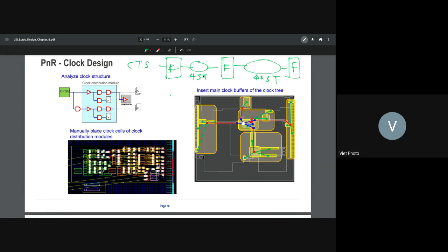So the thing is, because of 4 stage, I don't need this one to be fast. So that means even though the period from here to here is 1 nanosecond, now I will make the clock come in here, and the clock come in here, and the clock come in here. I make the clock arrive earlier. For example, this one is clock 1, this one is 2 and 3. So this one is clock 1.